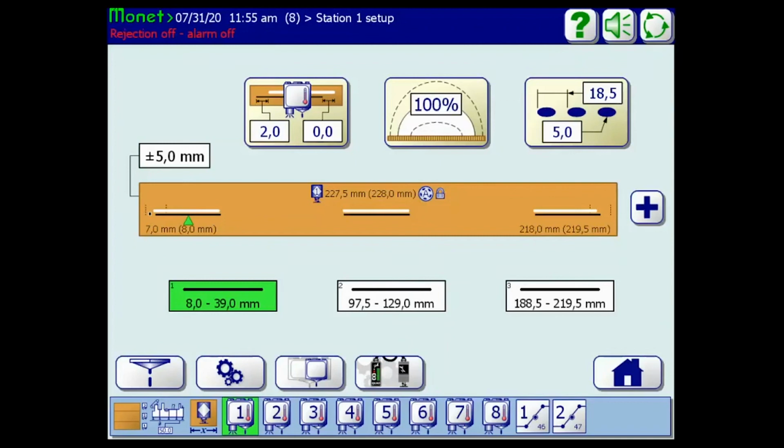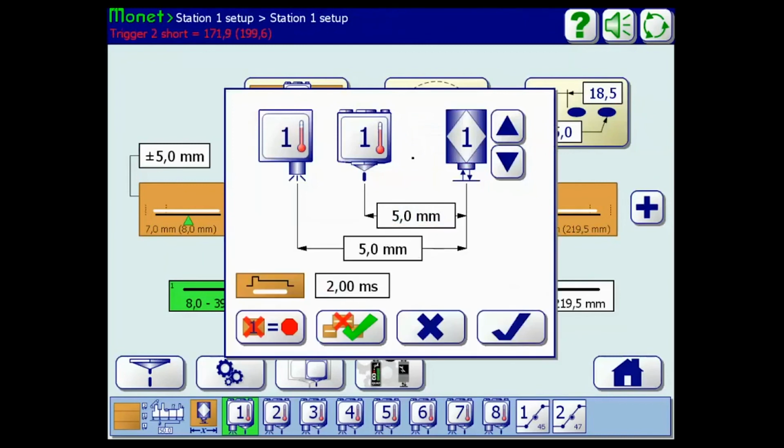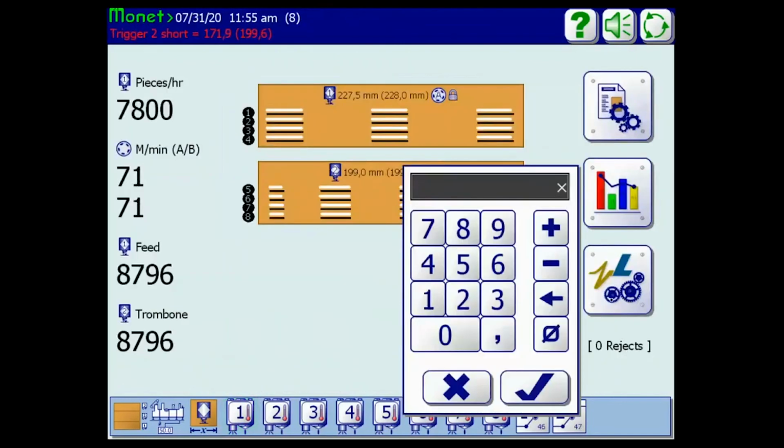We cater a lot to high speed applications that have folding scores. And if the adhesive goes beyond a folding score, it can create what's called an inside sticker. And if there's an inside sticker, that can create an issue with the fulfillment application when they go to put product inside the carton. The better your encoder resolution is, everything is dependent on setup. The system can be as accurate as you'd like it to be, as much time as you want to put into the setup, meaning are your lead distances as accurate as possible? Is your encoder resolution? The encoder, we have to remember, is the heartbeat of the system. Everything is relevant to the encoder pulses.